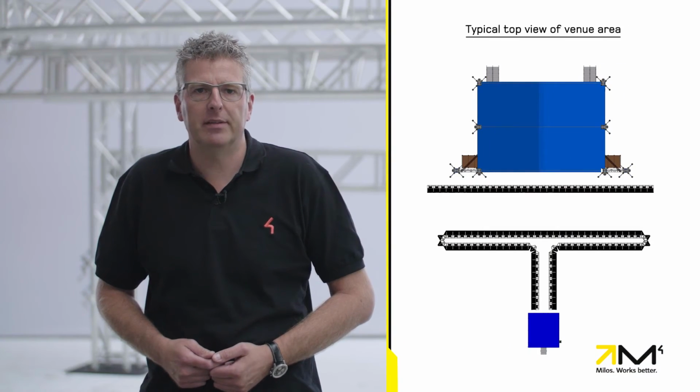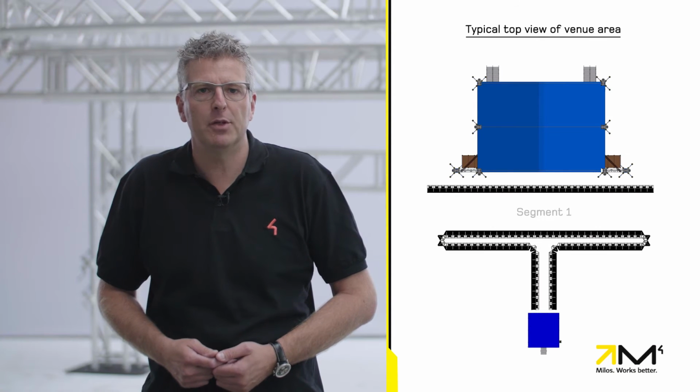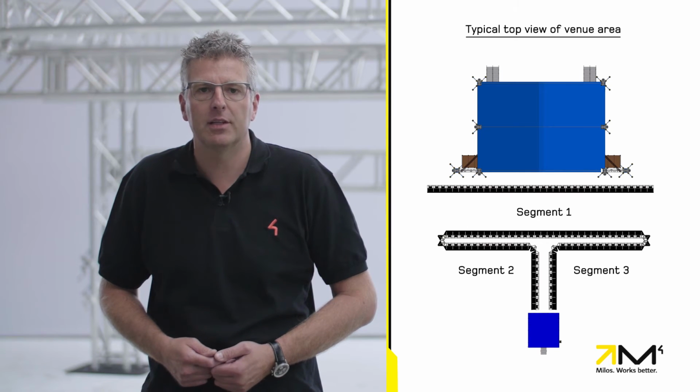If a large amount of spectators are expected, the venue floor should be divided into different segments in order to avoid excessive force on the barriers as well as on the audience in the front rows. This force can easily exceed local peak loads ranging from 500 to 800 kg if there is no segmentation. This can even cause displacement of a row of barriers. For security reasons, it's therefore necessary to have enough space between the front line of barriers and the actual stage.